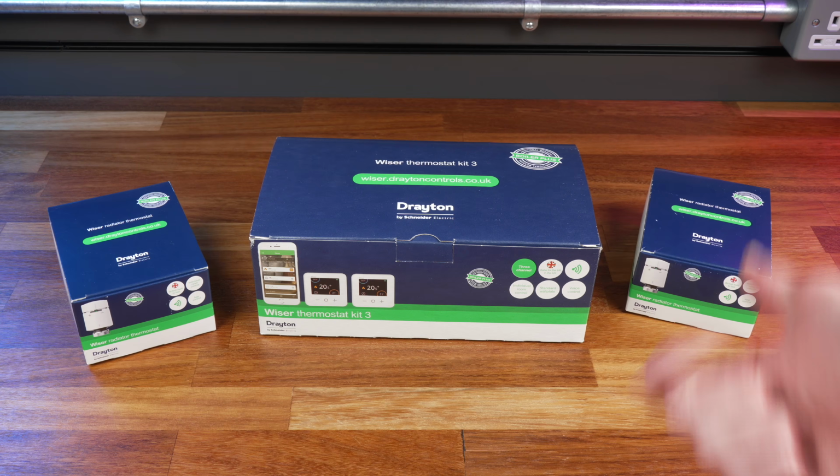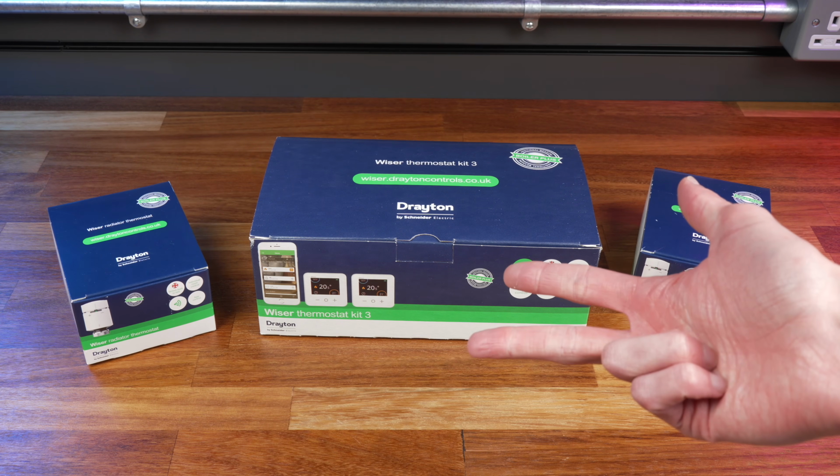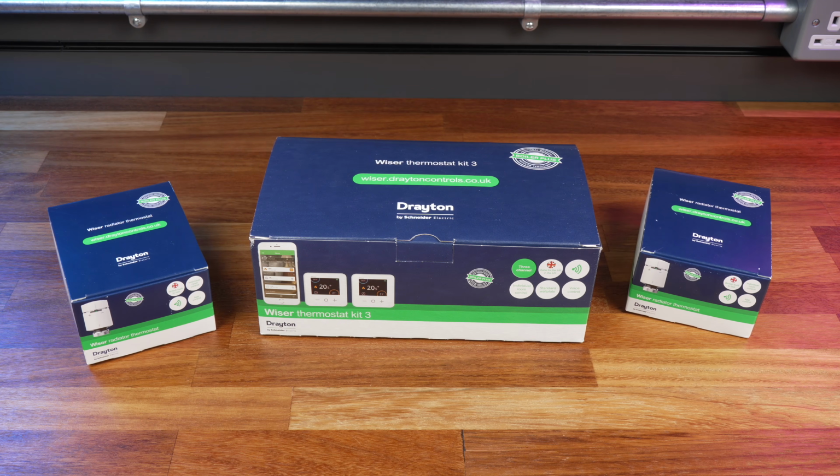There's a 1-channel version, a 2-channel version, and a 3-channel version. The 1-channel hub has a single switched output, and that's designed for combi boilers with a single heating zone. On the other hand, the 2-channel hub has a pair of switched outputs, one for heating and one for hot water. This is what you'd use if you have a boiler with a single heating zone and a hot water cylinder. And then finally, we have the 3-channel hub that we'll be looking at here. This has 2 switched outputs for heating, so you can use it with systems that have multiple heating zones, and it also has a 3rd switched output for hot water control for systems that have a hot water cylinder.